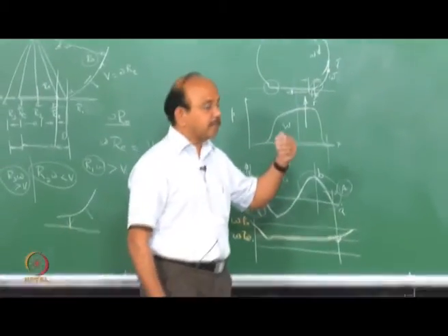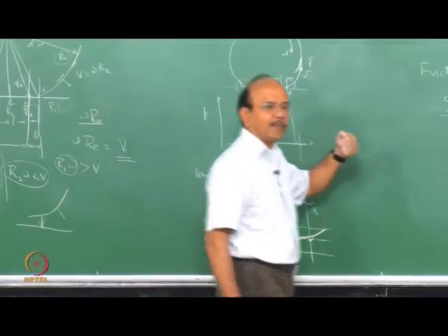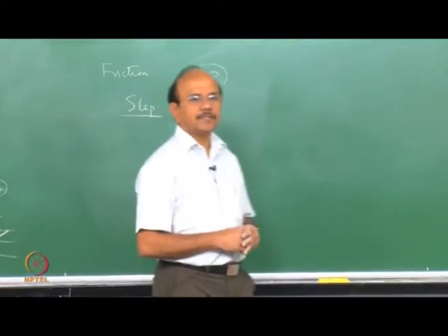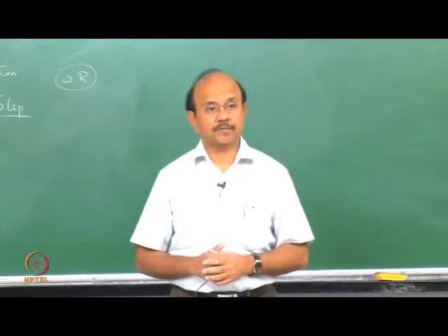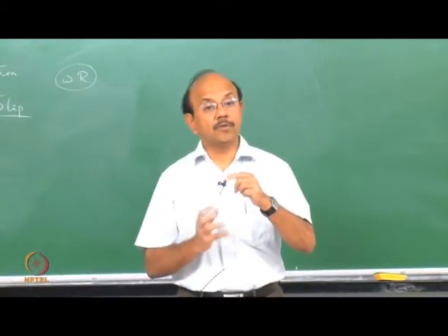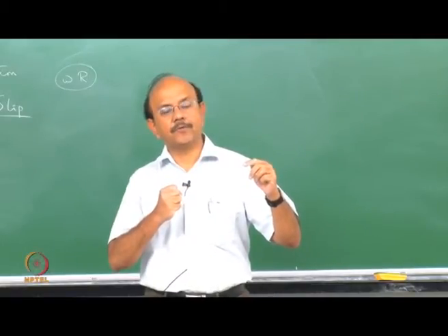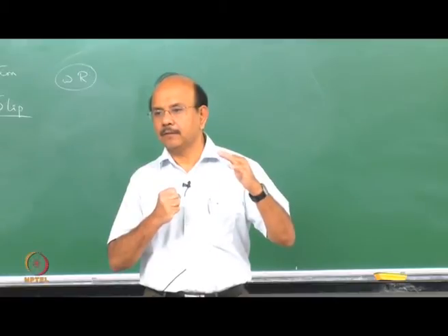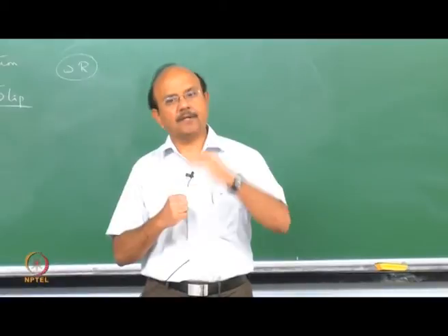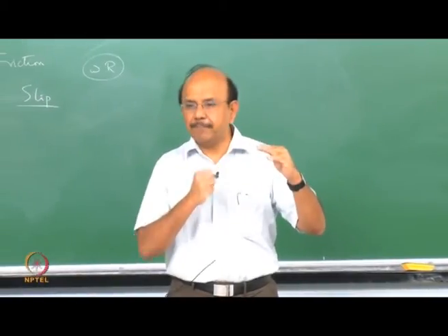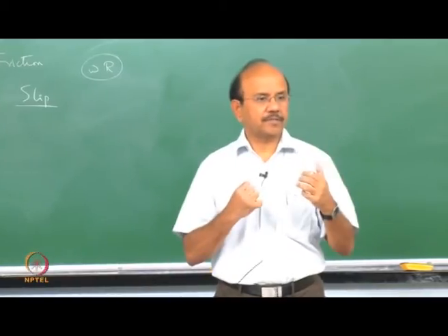Our next goal after this, this is actually simple when compared to what happens during cornering, because during cornering I have to develop a centripetal force, and the centripetal force is also developed because of this kind of interaction between the road and the wheel. And these tread elements, when I say tread, it along with the belt and so on, they participate in creating that force.